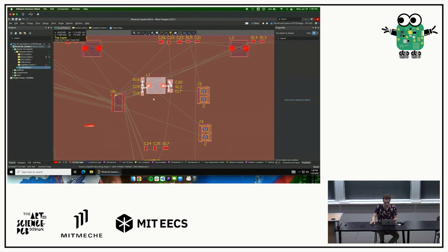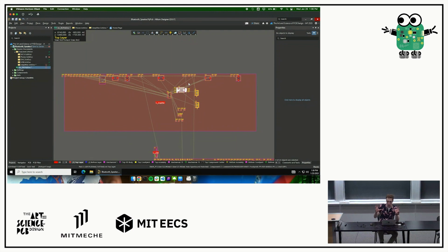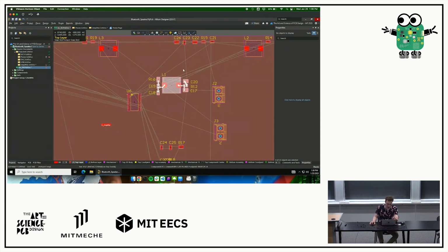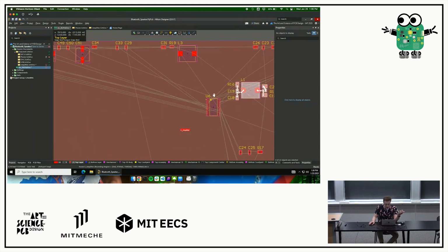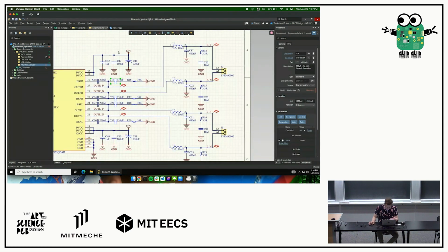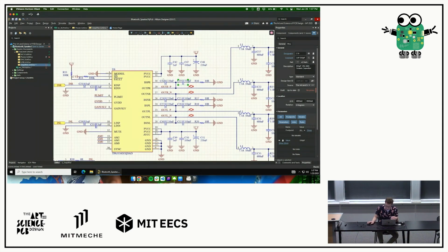But cool. So the trick here was to route a bunch of small stuff, put it together, and then play Tetris with this block we just made here, and then stick it next to the chip. Cool. If we wanted to do this for the rest of the amplifier, we could. This is only half of it. We could start turning our attention to things like the bypass capacitors, which we talked about the importance of in lecture because they need to reject noise from the circuit.